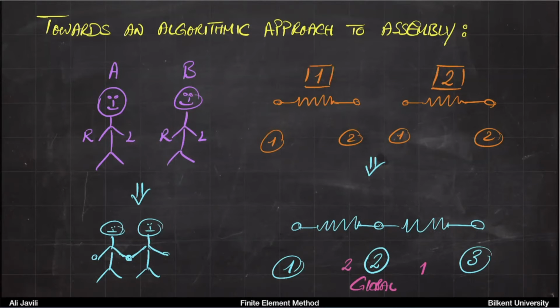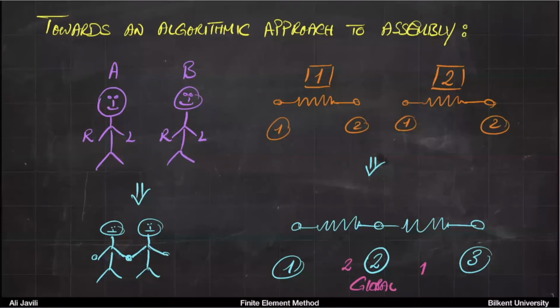And then I remove these right and left to make it more, let's say, mathematically meaningful. And now remember also downstairs we had A and B. Now those A and B would be 1 and 2. So you can think of it as this. Let's say this is N and this is N maybe. So if we write something like this, this means node 2 of element 1. So the superscript is the element counter. The subscript is the node counter of that element.